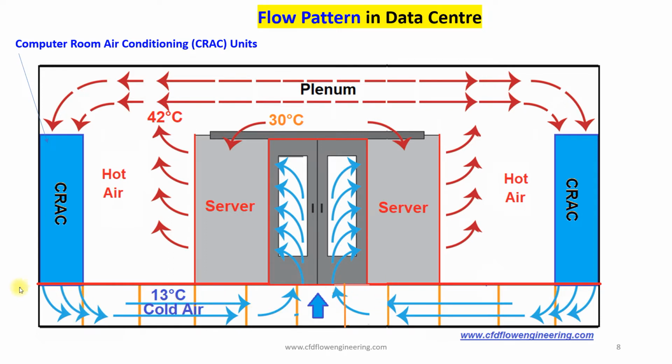The bottom floor is called the raised floor, through which cold air flows, then passes through the perforated tiles in the cold aisle part, then it passes through the server, because the server also has perforated openings on both sides to pass heated air.